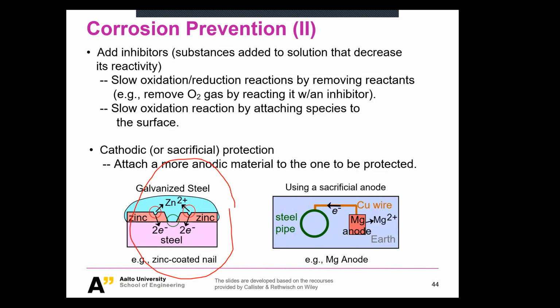For many steel sheets, we use a zinc layer to protect the steel from corrosion. But you may wonder why, since zinc is not a noble material, and zinc cannot develop a film or layer to go against oxidation. Why are we using zinc? The reason is pretty simple, because zinc is active. Basically, zinc is going to sacrifice itself, donating its electrons to the environment and developing all these bad surface qualities, to allow the steel to do its job in a proper way.